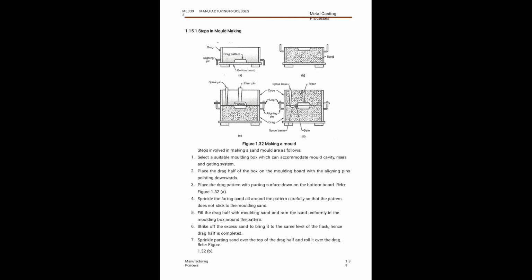First one, preparing of mold. The step by step sequence of mold preparing will be shown with a step by step diagram. First, select a suitable mold box which can accommodate the mold cavity. A riser and gating system will be selected.